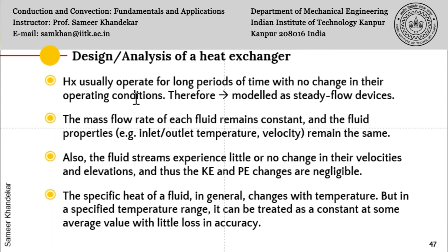Of course, as we have studied in the last lecture, the fouling may take place over a period of time and the performance may decrease a bit. But then routine maintenance is done to clean the heat exchanger also. So almost all heat exchangers are modeled as steady flow devices. So we are usually not bothered about the transient of the heat exchanger because it is small as compared to the total time in which the steady state operation is desired. In fact, it is minuscule, the transient.